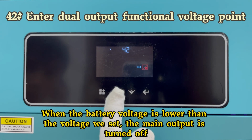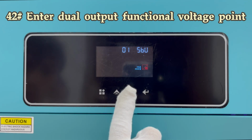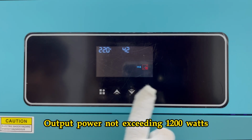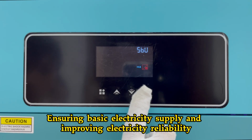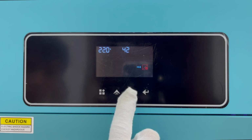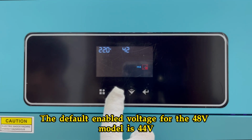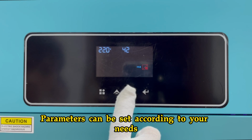When the battery voltage is lower than the voltage we set, the main output is turned off. The second output can still continue to supply power to critical equipment, with output power not exceeding 1,000 to 1,100 watts, ensuring basic electricity supply and improving electricity reliability. Parameter settings: the default enabled voltage for the 24-volt model is 22 volts. The default enabled voltage for the 48-volt model is 40 volts. Parameters can be set according to your needs.